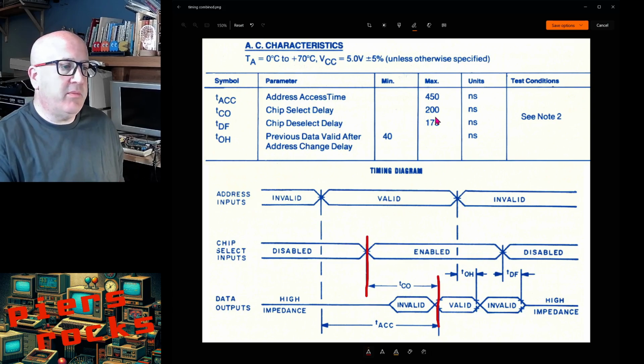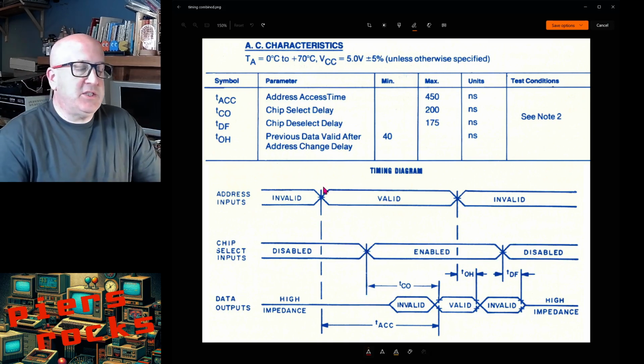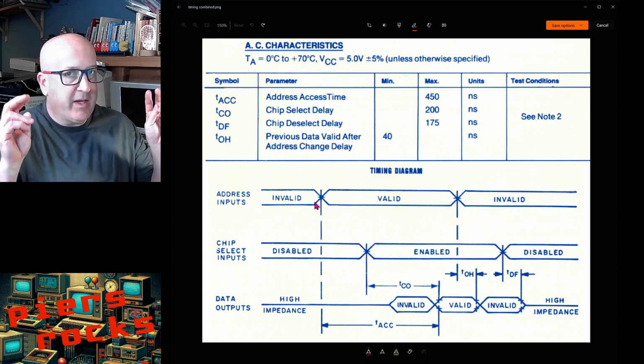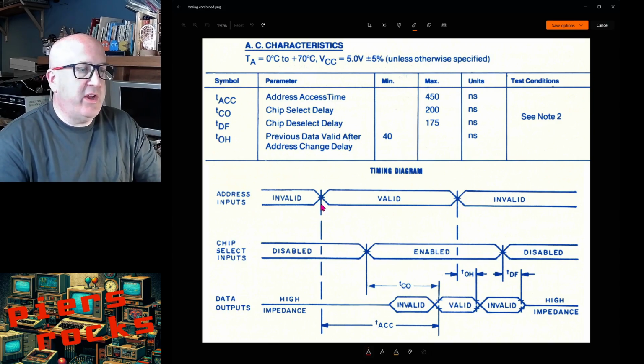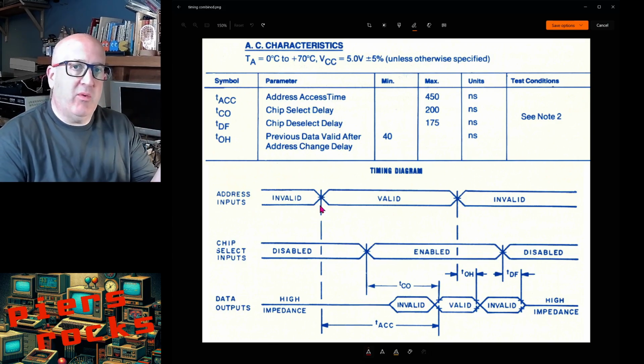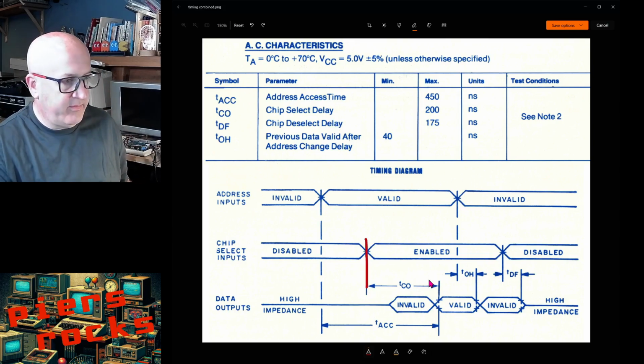time chip. So what that suggests is that the ROM chip is constantly keeping an eye, as it were, on the address inputs and figuring out what byte is at that address input and applying that to the data pins, but not setting the data pins to the output. It only sets the data pins to outputs once it notices the chip select line going active.